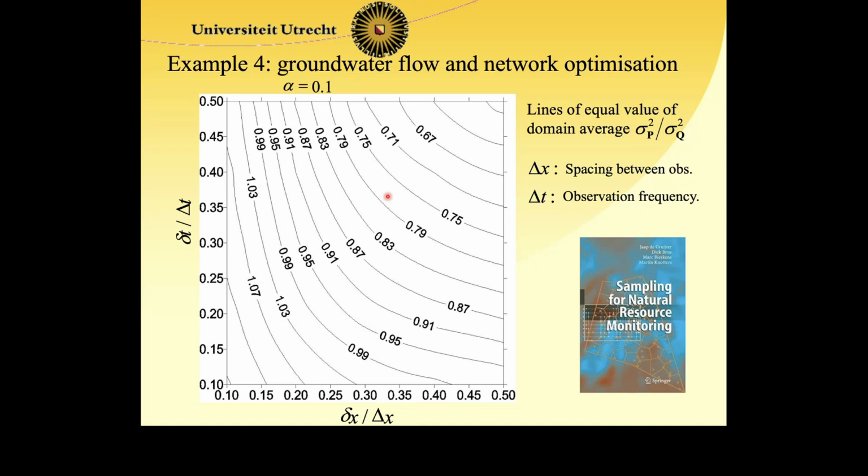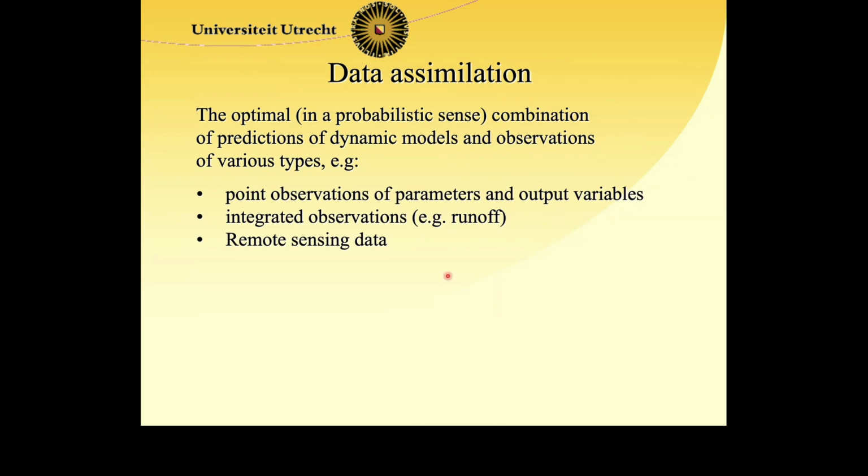Well, state estimation is where you have a state equation and you estimate either a static or dynamic state in time using observations, optimally combining state predictions or time updates with measurement updates by ingesting the observations through the linear Kalman filter. And this is actually one particular case of what we call data assimilation, which is a much wider range of research than the Kalman filter or state estimation itself.